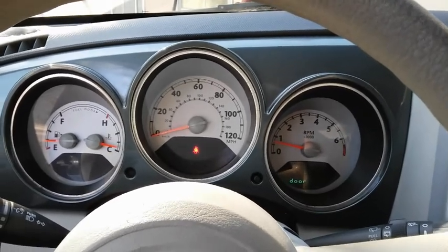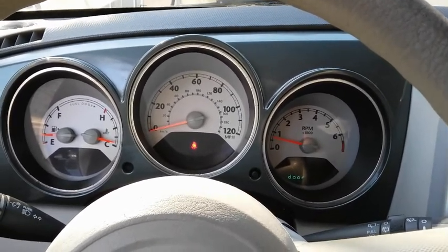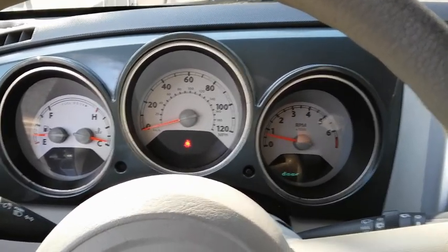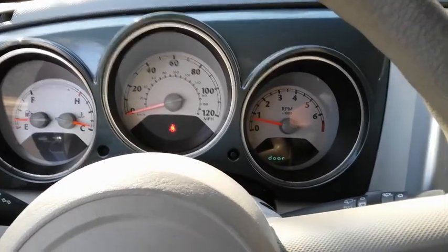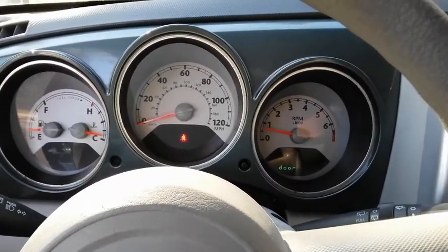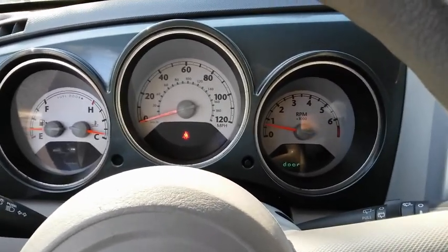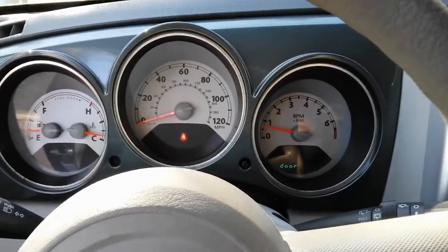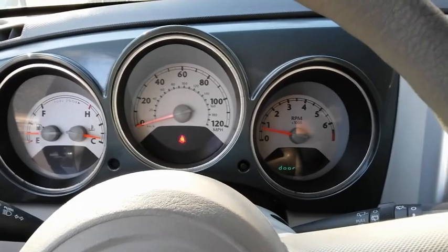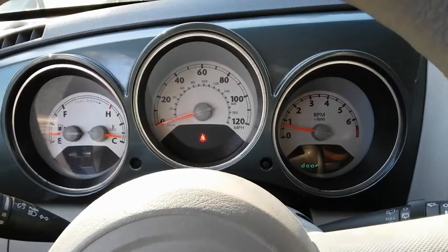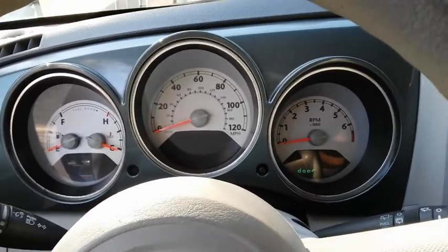So luckily that glitch didn't stay on for longer, or else I would have probably shown you guys that if the voltage would have dropped back to 0 and then went back to 12 and stayed there constantly, a steady 12, then I would have come back to the vehicle, turned the vehicle on, and this oil light should have turned on, showing that intermittent fault on this oil pressure switch. Means the contacts got stuck open. Alright, so I'm going to turn the engine off. So I'm going to go back and show you guys to see if we could capture that glitch once again.